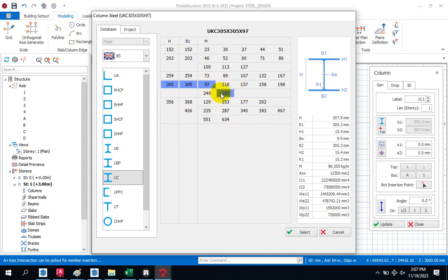But the good thing about steel design is there's what we call utilization ratio, and there's what we call slenderness ratio. So this utilization ratio and the slenderness ratio will help to tell us if the steel cross section could pass. It will help to tell us whether the cross section is too large or that cross section is too slim, which is the slenderness ratio.